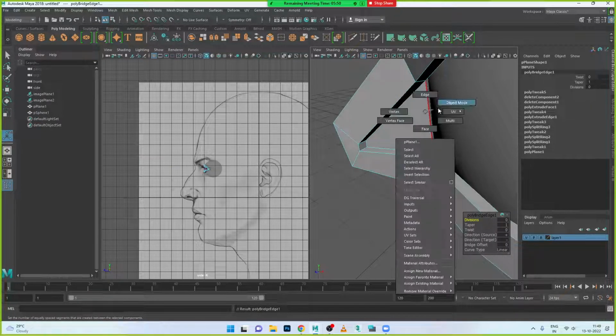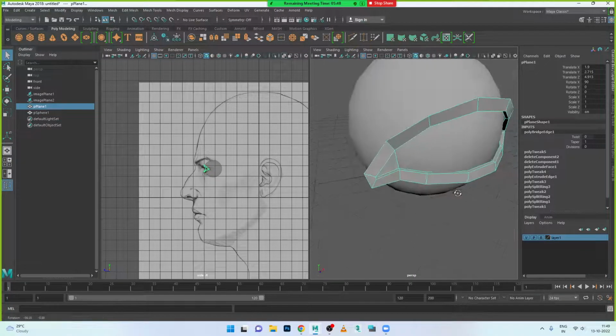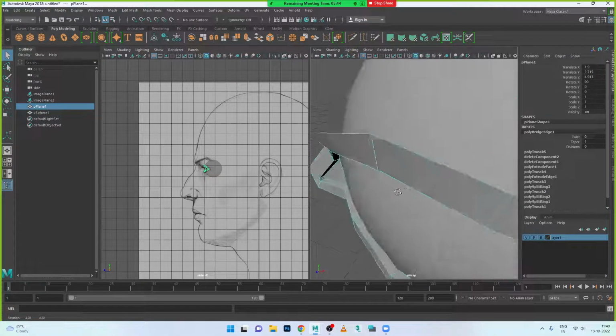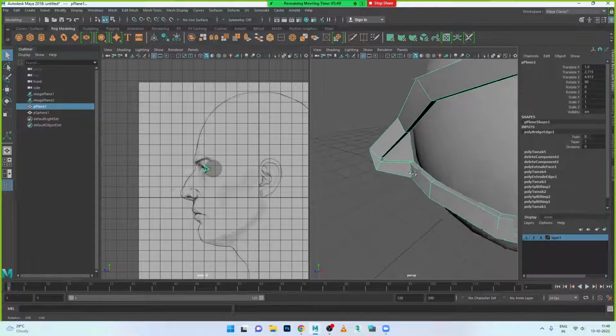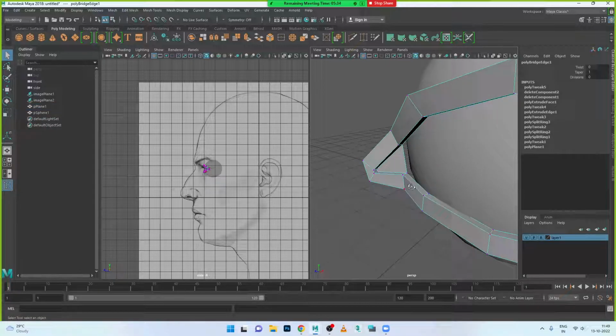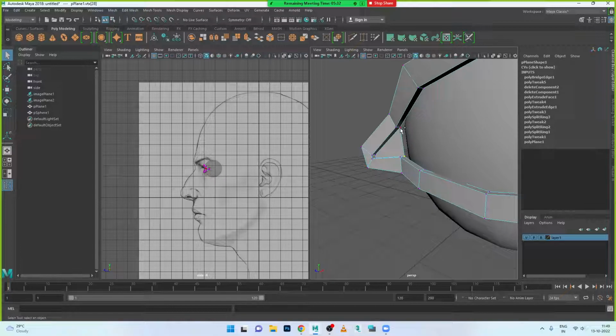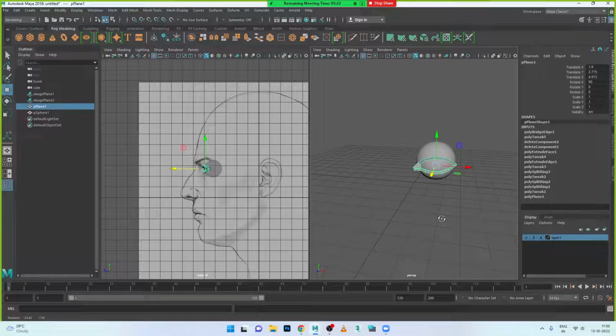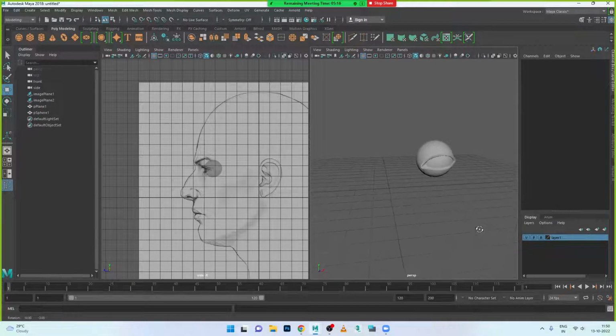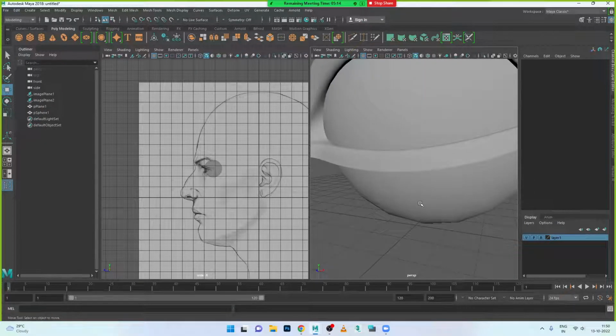Okay, right click on this one, again object mode, and see once, zoom and see if any space is left in this one. You can see a small gap is there in this one. What to do with the gap? Don't adjust the outer area, only the inside area we need to adjust. Now go to the vertices, select this vertex and this vertex, move tool and try to move it inside this one. Then right click, object mode. Now press 3 and see once. Right now it is done. Zoom and we can see here now.